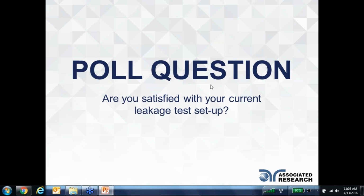Thanks for that feedback. You know, I would say everyone needs to rethink it maybe every year just to verify we're doing it safely and most efficiently, and that our operators are safe, especially because most people are probably running high pot and ground bond along with line leakage testing. Something that I haven't gotten to was this standards reference guide that we saw for 60601-1 earlier in our slides. That's a cheat sheet we've created for our customers that Allison can shoot out to everyone to give you a basis of where to start if you're one of the 9 or 18% that thinks there's improvement needed or needs rethinking.